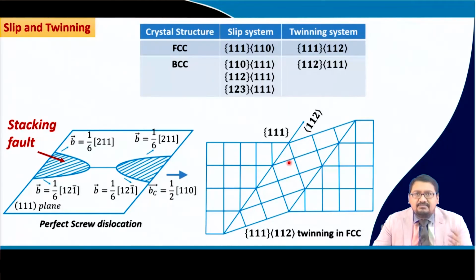So, in some cases when there is an increased activity of a certain slip plane and slip direction, that activity is going to influence the texture evolution. In other places, if that activity is lesser and there is another slip activity or another twin activity, that will influence the texture evolution. We can say that a deformation behavior in a polycrystalline material requires multiple slip systems, and